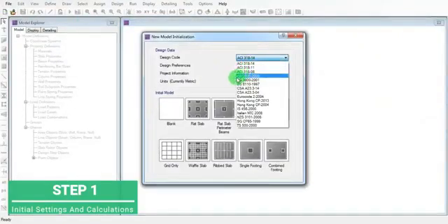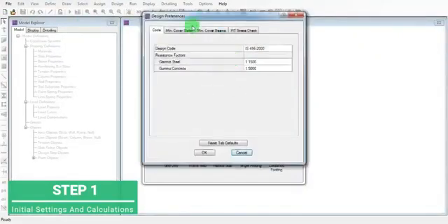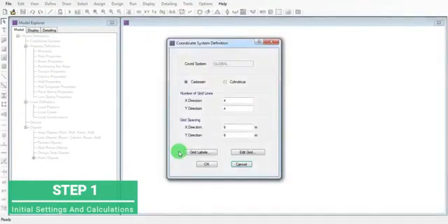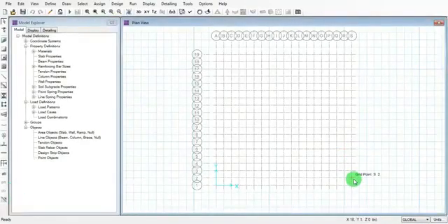Now go to the software and set IS 456. Then add the cover and rebar options. Then set the grids. That is 18 meters we have, so the grid lines will be 19 numbers in both directions. Now set 1 meter. This is how we got the grid.